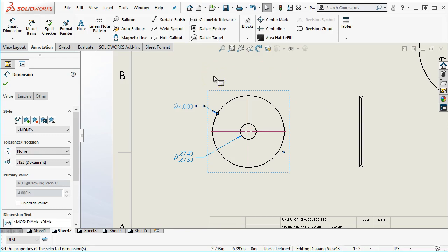So to get us started, we have those form tolerances. And so what I want to control, what are my critical dimensions, I just called it out right here. As soon as I put that, hey, this is critical, then now I'm starting to think, how do I control that? All right, and then with our form tolerances, not always, but 99% of the time, we're going to pick something to be flatness to act as our primary datum. So that establishes the form, establishes where the datum is going to be produced.